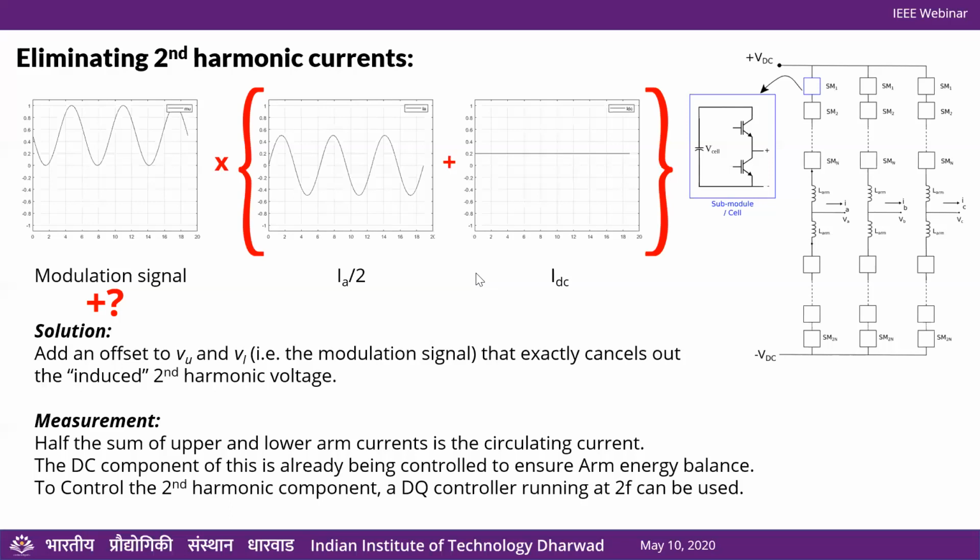Okay. The next question is, if we say that MMCs have less harmonics than a two-level converter, why can't we use it to drive a motor and reduce heat dissipation and other losses? Okay. So let me address this first. MMCs have significantly higher complexity. They are way more complicated to control and modulate than two-level inverters, right?